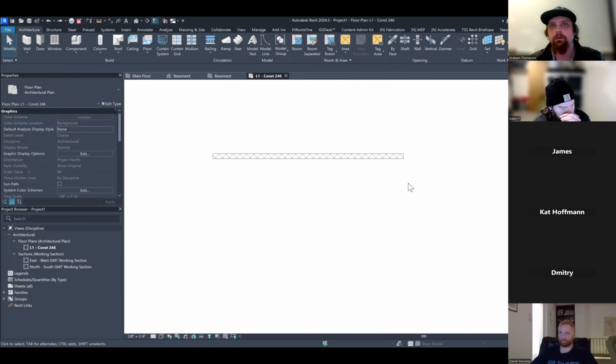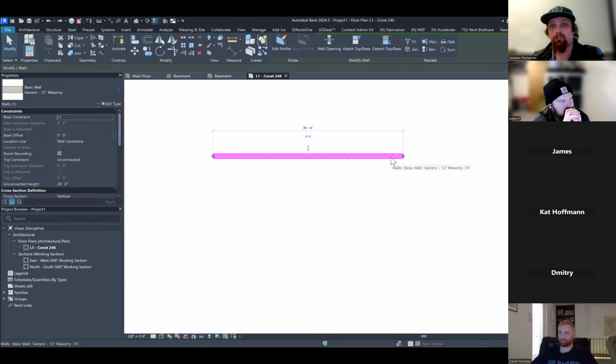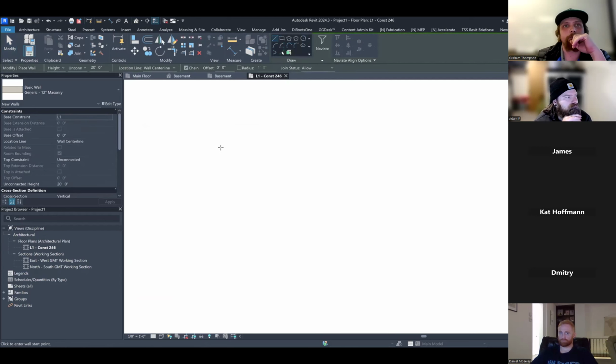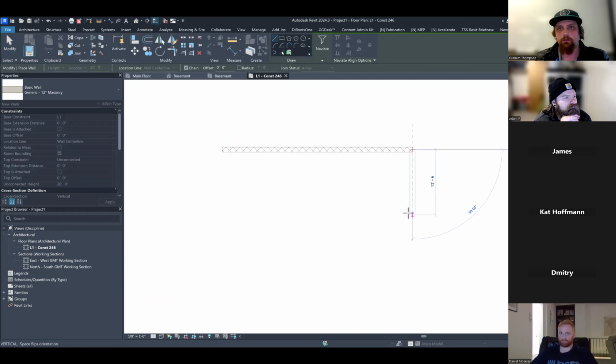So again, I'm going to start over because we only have 1 wall in, right? And I'm going to do this with 2 clicks. So let's do it again. Okay. Click 1. To the right, 36 space 6. Down, 7 space 6.